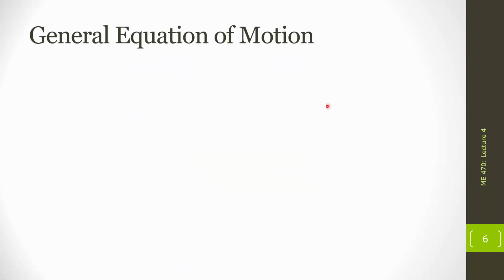We're going to find a general equation of motion for these types of systems. Again, a little bit more complicated because our right-hand side is no longer 0. So we're extending what we saw in that last section. We now have our left-hand side having our dependent variable, here just using x, and then our right-hand side has some forcing function f of t. When we're writing our equation of motion, we generally want to put our dependent variables and its derivatives on the left-hand side, and any pure constants or functions of time explicitly on the right-hand side.